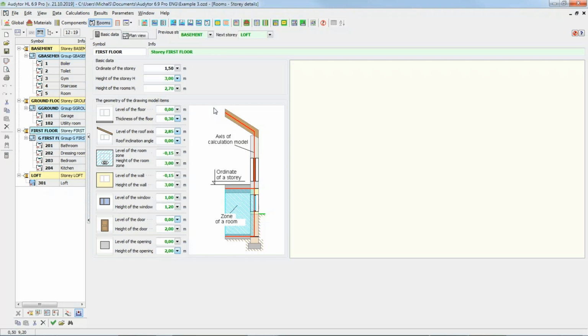So you have to learn it, but after learning it, you will see that really you can save a lot of time. So generally, the principle of inheritance is that we can create some information as default for the whole building, and then we can modify it if necessary at lower stages, for example, at the step of the story, or at the end as a kind of exception for the specific element.